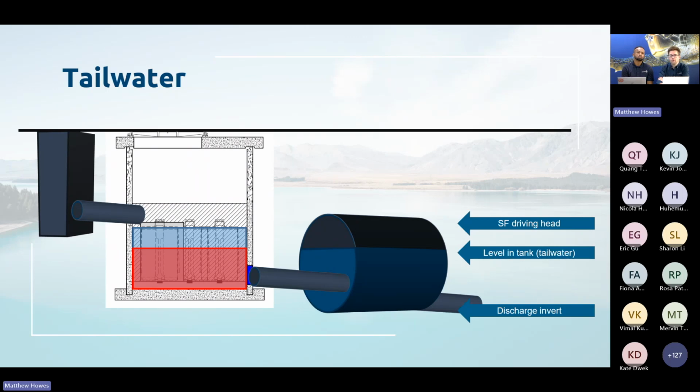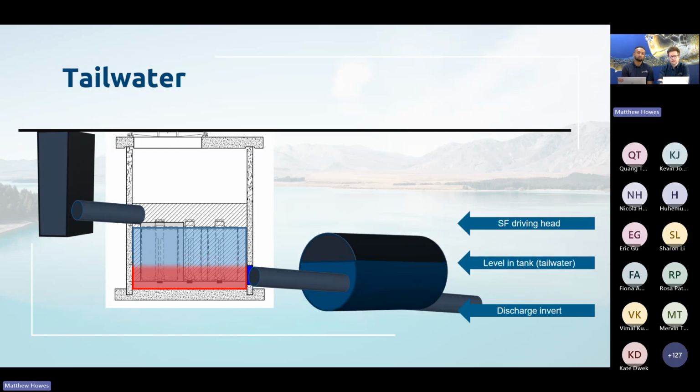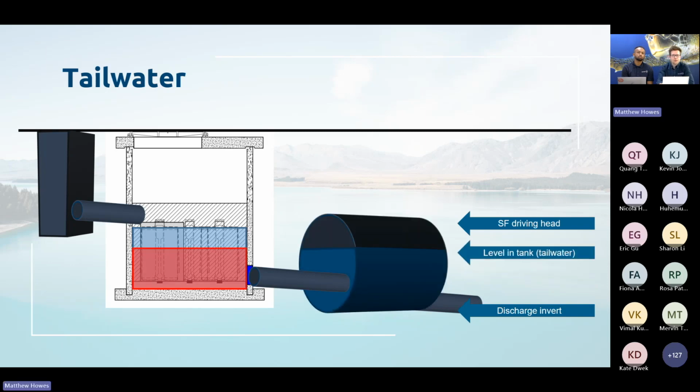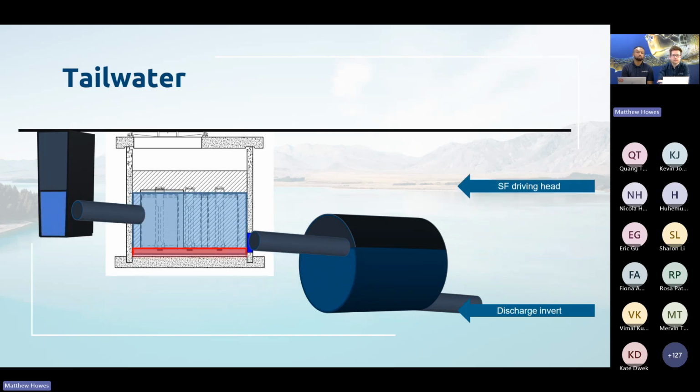So there are a couple of options. You can either lower the tank, lower the discharge invert, but oftentimes it's not quite that simple, unfortunately. So the first option is to lower the tank, change the tank design. Can we design our cells to avoid the problem entirely? Where that's not practical, though, the second option, as Johannes mentioned, is to raise the StormFilter.